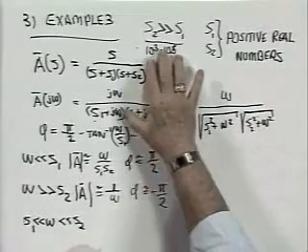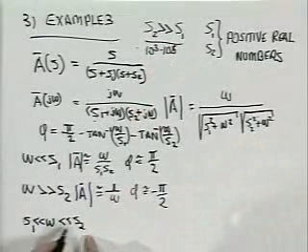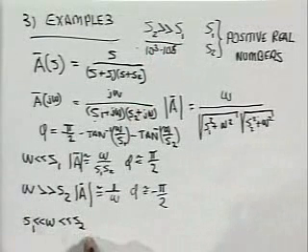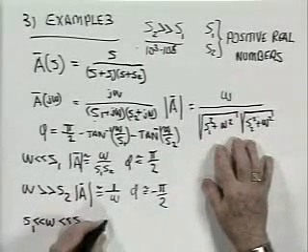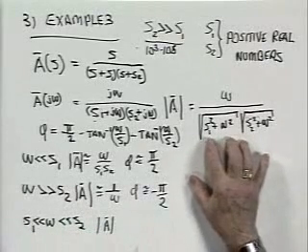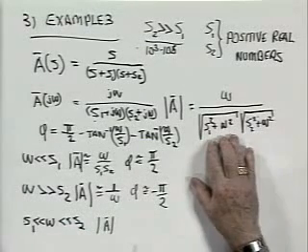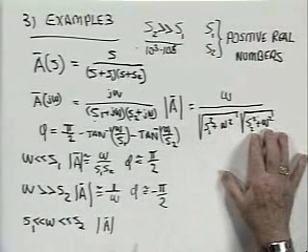If these are separated by 3 to 5 decades, then there will be some frequency range in the middle in which omega is much larger than S1 and much less than S2. If that's the case, then for the magnitude of A, S1 is negligible in the first radical, omega is negligible in the second radical.